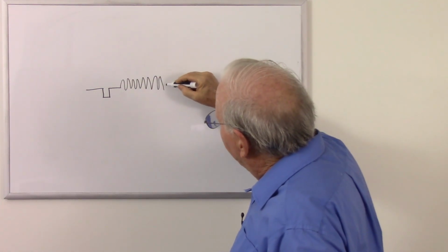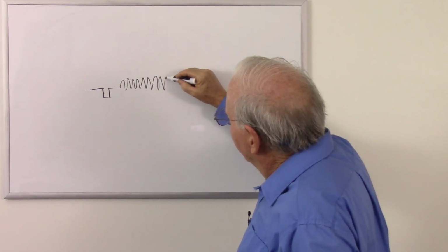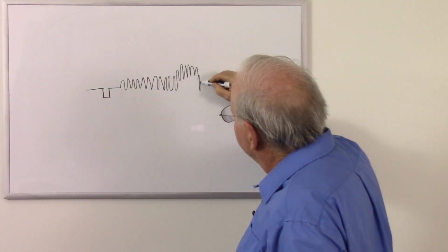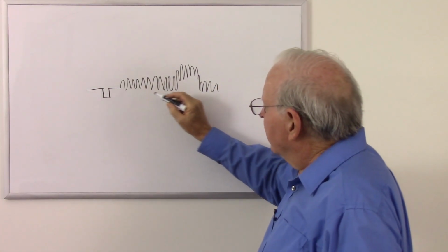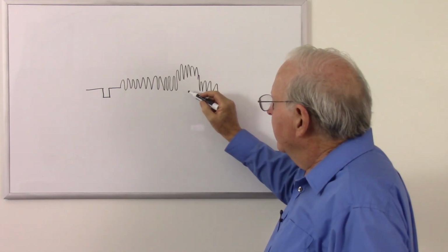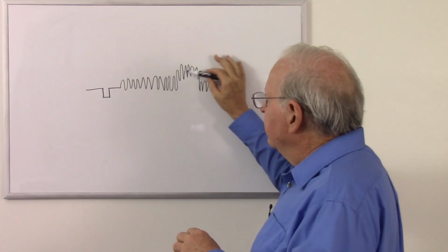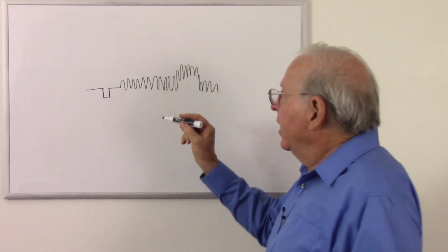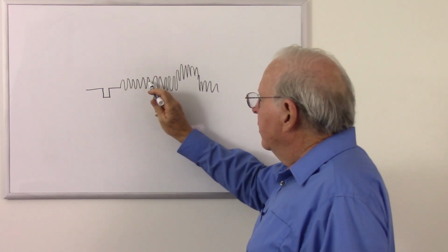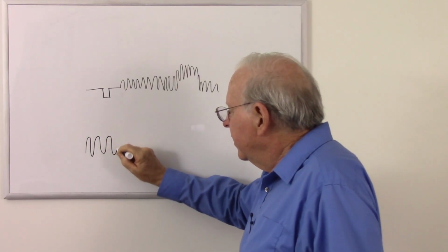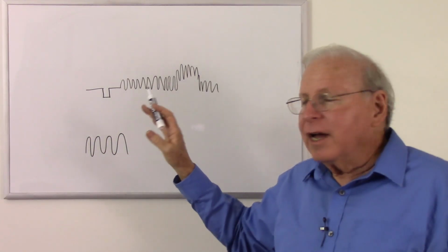And as we hit a light spot, the whole thing is going to be shifted up and then shifted down. So instead of just having a little blip there for the candle, we're going to shift that whole thing up and down. So the mean level of this gives us our luminance, but then the phase angle of this compared to our master is going to tell us what color it is.